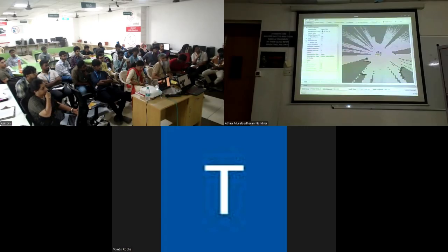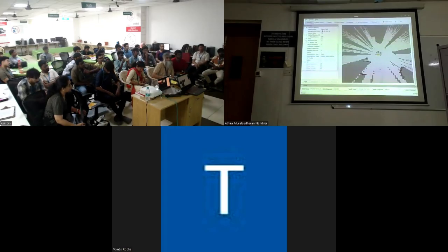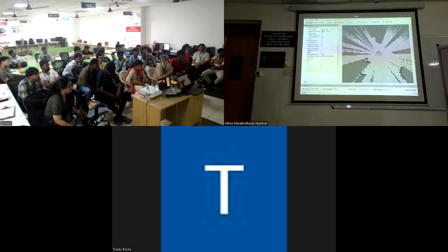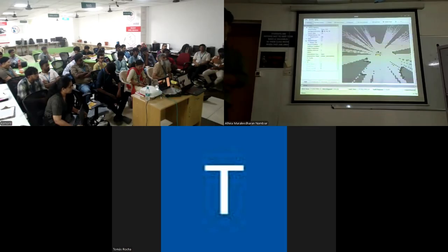Nowadays one is using only the radar. Actually, we have made this as a custom build, so any kind of sensing that we have to do, we can add it. One is with the radar, and now we are working on integrating vision together with the radar. We are using both to build a map, taking both inferences. The reason is that the radar only recognizes the first level, not the lower surfaces, because of which we find difficulty navigating through an unknown environment.